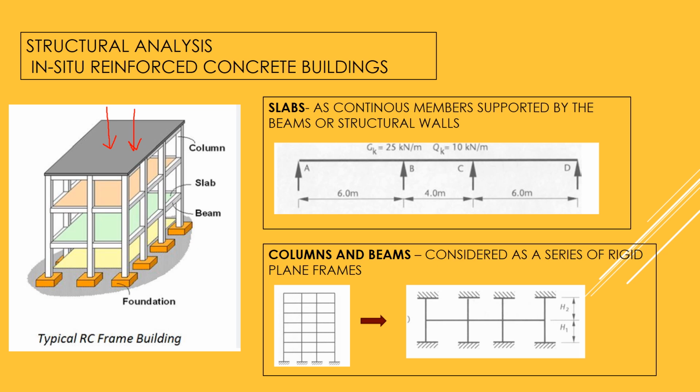When these external loads act on structural members like beams, slabs or columns, the elements will deform, and at the same time it creates some stresses within these structural elements. They may be bending stresses, shear stresses, torsional or twisting stresses. Structural design aims to design these elements according to these internal stresses.